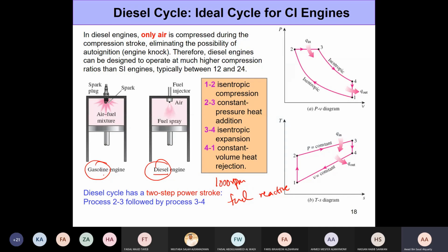It may or may not ignite completely. And if you put gasoline in a diesel engine or a diesel car, you will also have problems with the fuel injector, because gasoline is less viscous. It will not lubricate the fuel injector properly. There are tons of other issues, but in terms of combustion, it may not ignite completely or immediately.